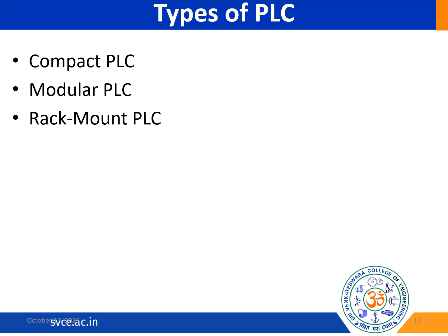This is a type of high-end PLC, which is specifically designed for complex and demanding applications. It has a maximum number of input-output points. Rack mount PLCs are very modular and can be easily expanded by adding additional modules to the rack. When you consider this, we have input output embedded in the compact PLC, and we have modular PLCs where we have the power supply, CPU, analog input, analog output, digital input, and digital output.